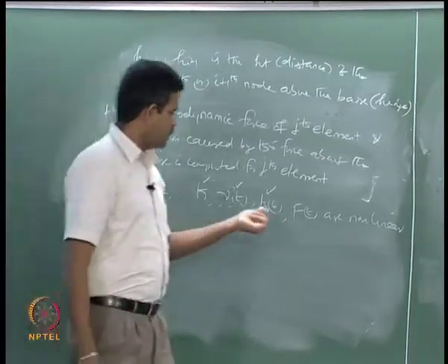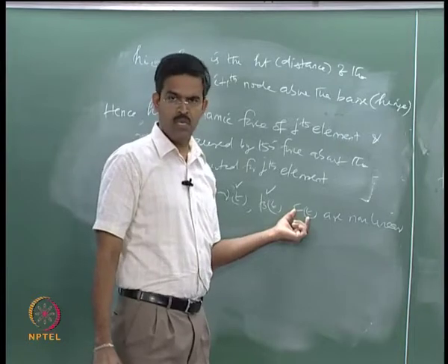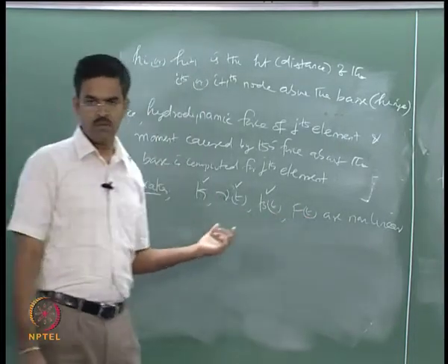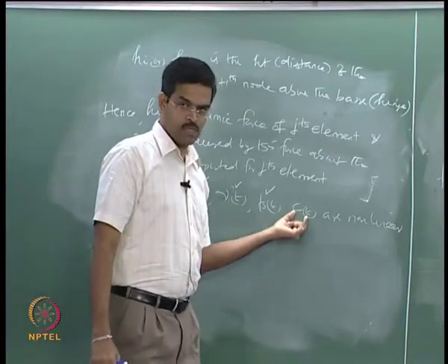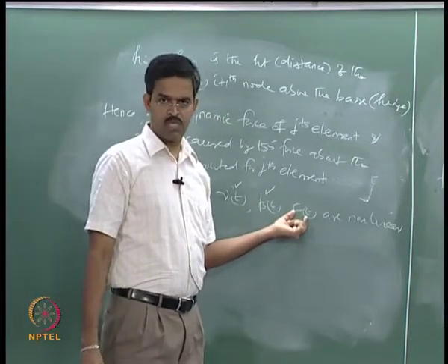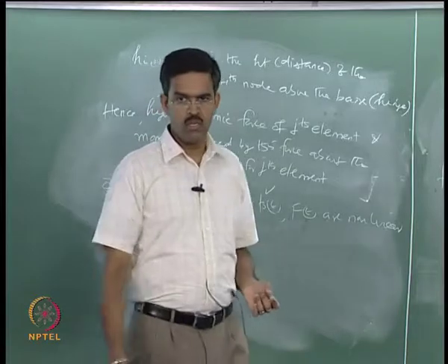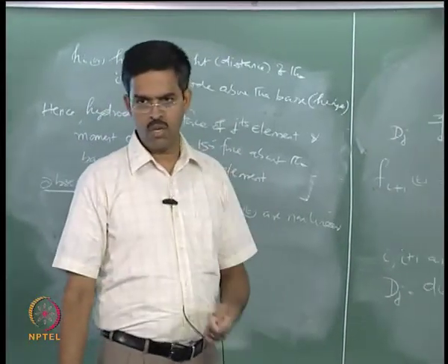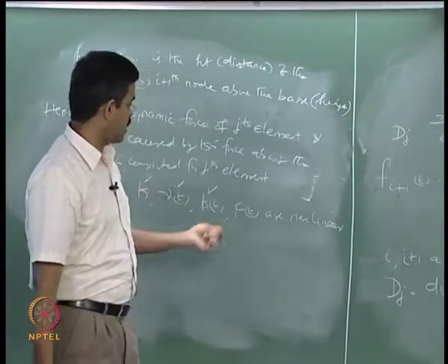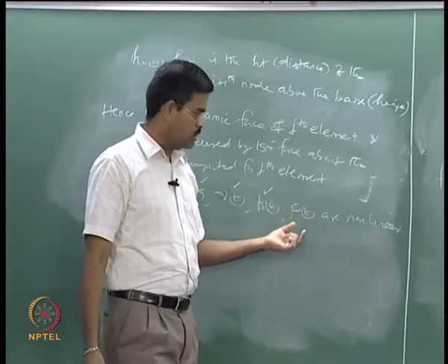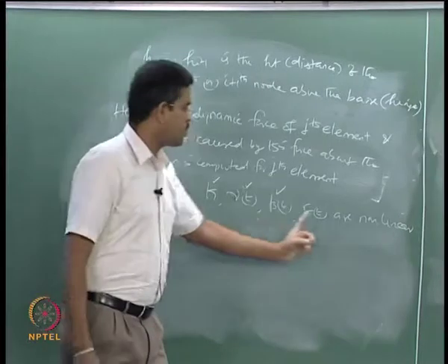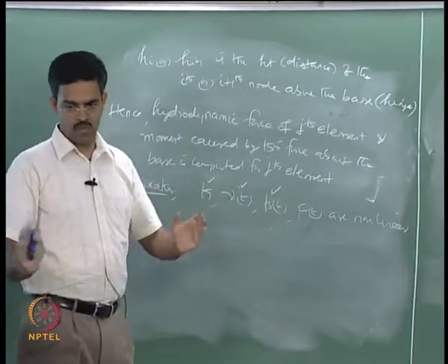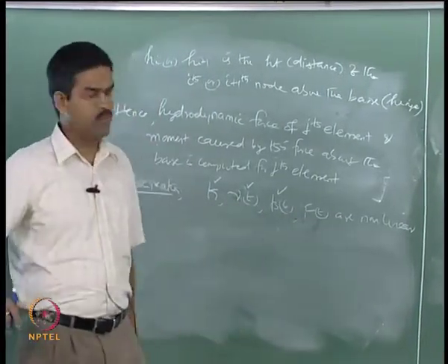I think you will very well appreciate why f of t is non-linear, because of the drag term present in the hydrodynamic forces. You also have non-linearity from the drag term present in the aerodynamic forces, because if you see it as a v square, they are also in pressure drag in aerodynamic forces. So, there is a drag term present in hydrodynamic as well as aerodynamic forces, therefore, f of t is also non-linear.